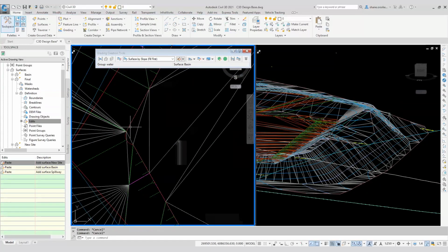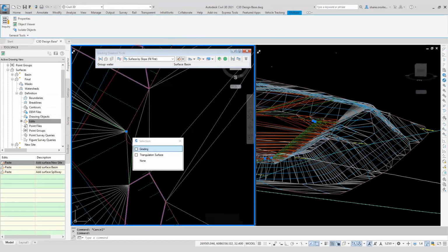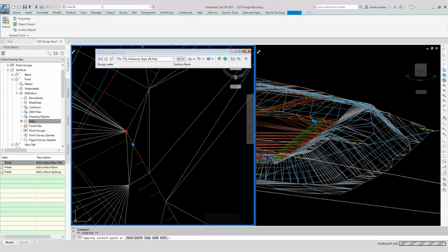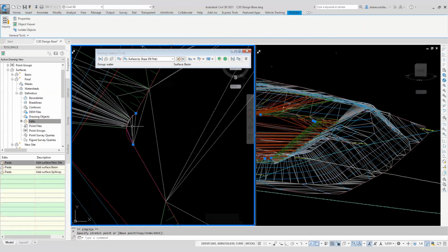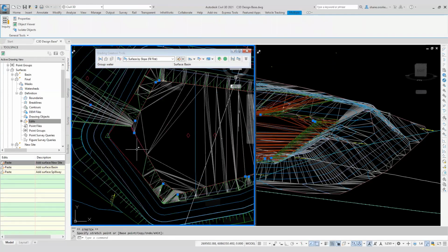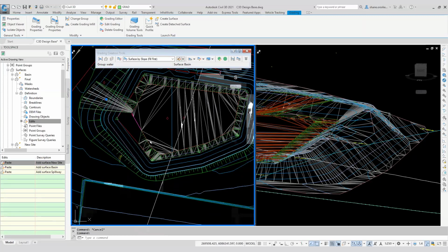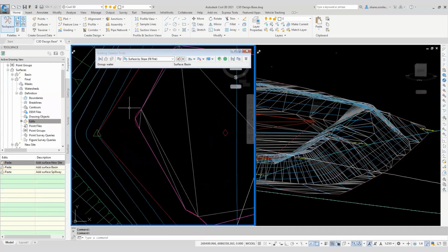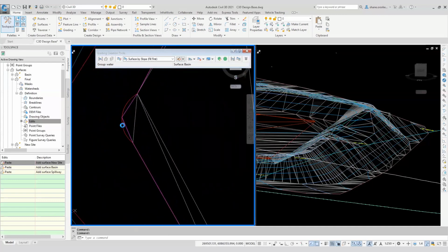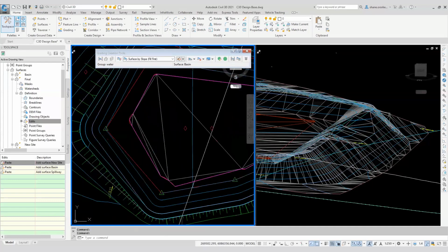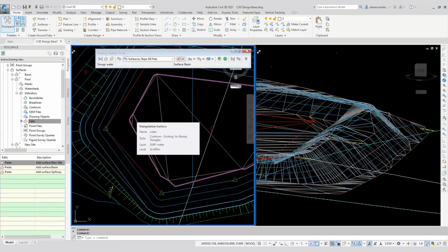Yeah, I mean, look, there's some gradings that never meet, right? And that sort of causes Autodesk a bit of grief, having a think about how things might meet. If a grading is being silly, then you can just delete the grading. Look, typically it's a lot better than it ever used to be. I don't have it crashing like it used to in old versions, but certainly sometimes the results don't appear to make a lot of sense to the user.